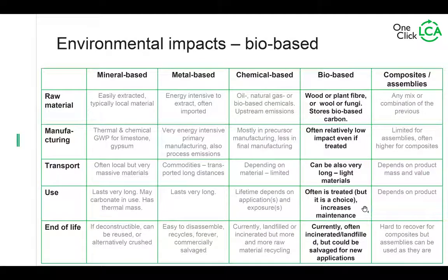Timber is often treated in use, but it is a choice in some cases to do so, and it increases the maintenance, right? So if you do a timber facade and if you choose to paint it, or if you have to paint it, you actually make a choice also for having those life cycle emissions associated with applying paint so and so many times.